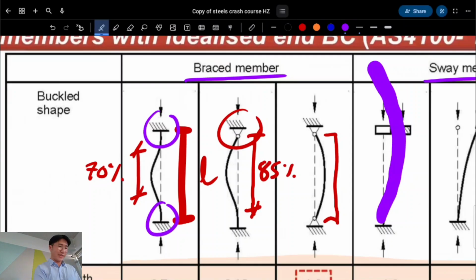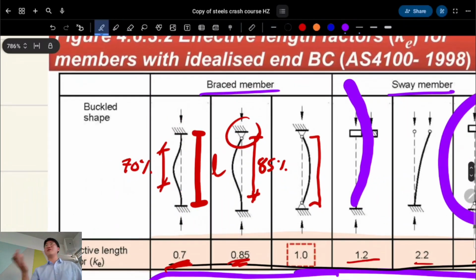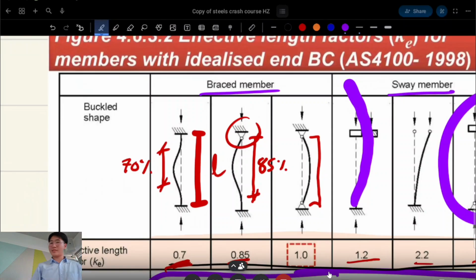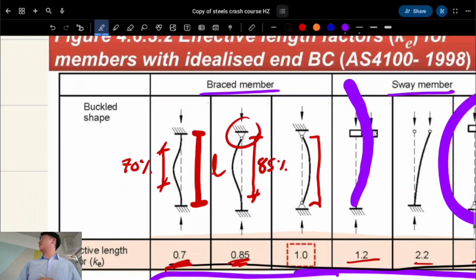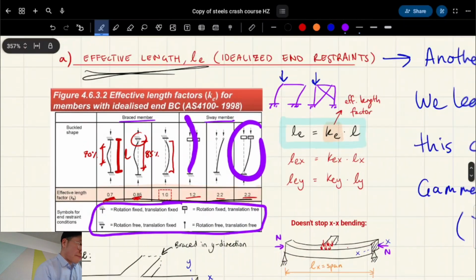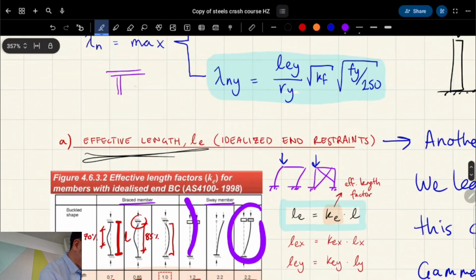Does anyone want to have a crack at this? Actually, this is an anecdote. At work, the first thing I've really been learning, because I just started last week, is about columns and designing columns. And so I'm designing, do you guys know Scape? Okay, it's a building similar to Scape, Kingsford, on Anzac Parade, so it's a residential building. So it's a concrete slabs and columns system. What kind of effective length do you guys reckon they would consider for that type of building? Right. So let me just quickly draw it. It's kind of like this shape.